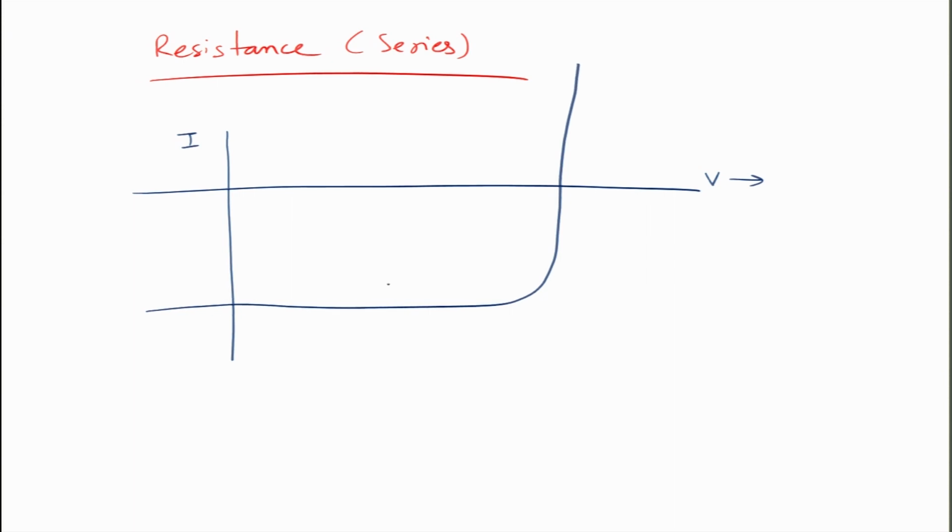the series resistance tends to affect the curve. So for a good device, series resistance should be 0 or as small as possible, whereas shunt resistance on the other hand should be as large as possible, so that you have minimum leakages. These are the two basic concepts. So, now series resistance from this is going to be worked out from the slope of this plot.